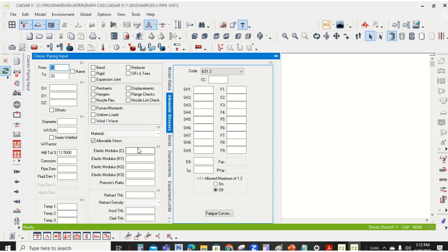So now that we have our unit, the node is to help us create the elements, the pipe, the elbow, the rigids, the valves, the flanges, and other items. So we give them a node from one node to the other. And our node range is 10 to 20. It is good to choose 10 to 20 because if you want to insert an object, it will be easier for you to still choose. You can still use 10 to 15 or 10 to 12, so you have more leverage on node numbers.